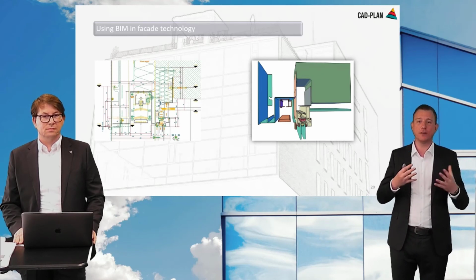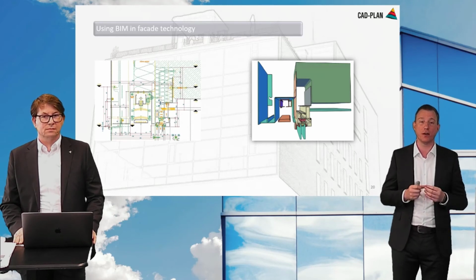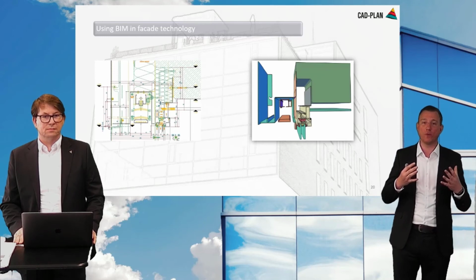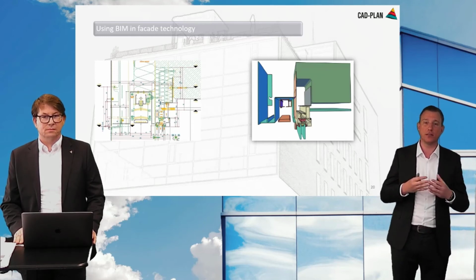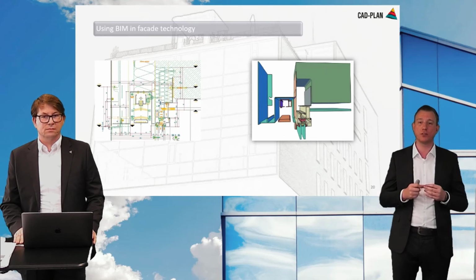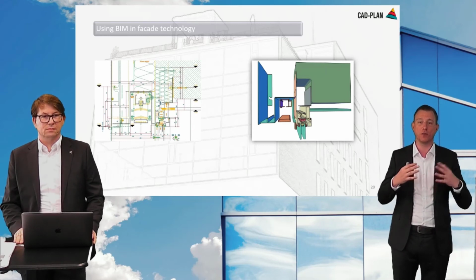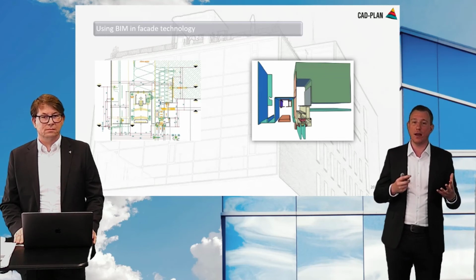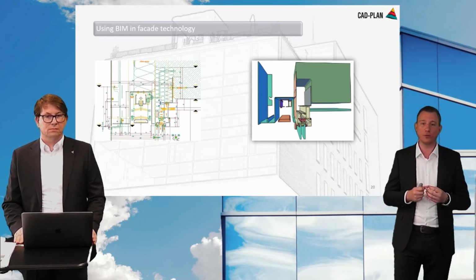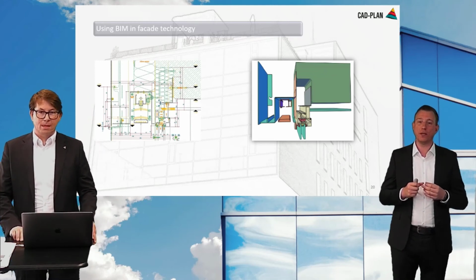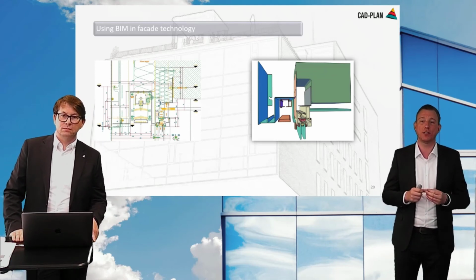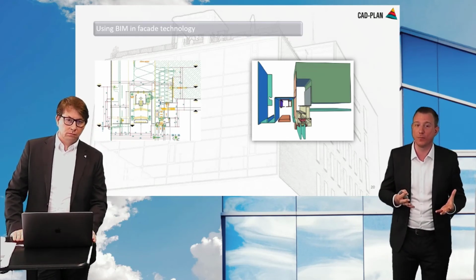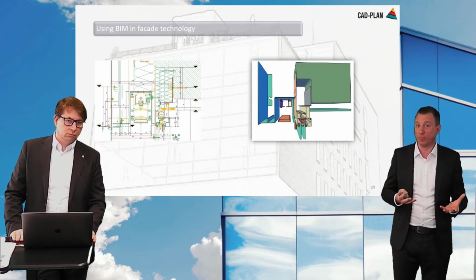of a high detail for the required information. A simple representation of the facade, for example, the sheet metal or the different parts, the sun protection, would be completely sufficient. If it is agreed with the client, a LOD of, for example, 200 would be sufficient, and they provide digital 2D plans and text information, for example. This would also be BIM.